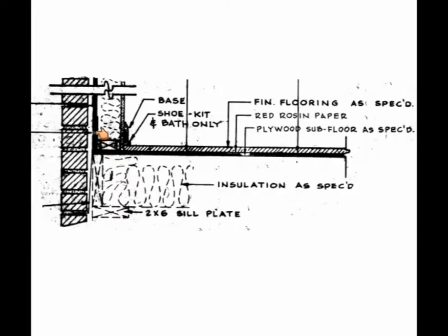On page 12 of your construction documents in the wall detail, that also shows you that the floor system goes to the exterior face of the stud for the exterior wall. Here is your stud for the exterior wall. Here is your floor system. So the edge of the floor system lines up with the exterior side of the stud for the exterior wall.